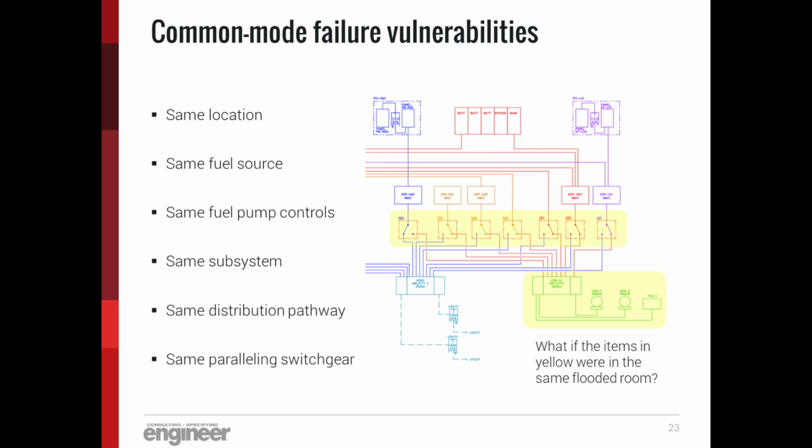Let's talk about the emergency electrical system. Any part of the central electrical system, as an example, using the code phrase, where you've got redundant equipment in the same space. Say, for example, two critical branch transfer switches that feed different critical branch loads, where the loads themselves are considered to be redundant to one another.